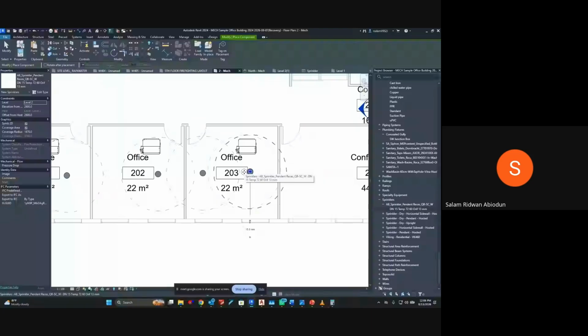When it comes to a partition, the partition takes preference. I mean, we have to consider the partition. Because if we want to be adamant that you must have that 4.6 minimum sprinkler space, you might leave some place that is actually a partitioned space, and fire can go up and come into that place without you having any protection for it. Do you understand?